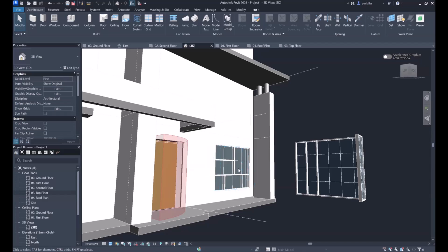I've lost some. Where are you right now? I saw the curtain wall. In the wall. Go in 3D. Yeah, you cannot see it, but you know the place where you put it. You know where you drew the wall. Yes. Yeah, go around that wall. Just try to act like you want to select it. You will see. No, in 3D. Or you select the wall, you hide it. Then you will see your curtain wall will be there.